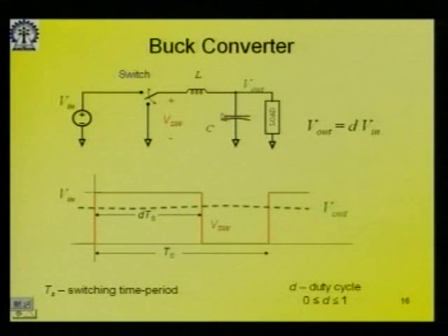Now, assuming that as a base condition, you can analyze the entire circuit in a very simplified fashion, because under that condition you know the voltages across all the points: the voltage across the switch node at different instants of time, and the output voltage. So, given the two voltages across the inductor, what will be the current through it?